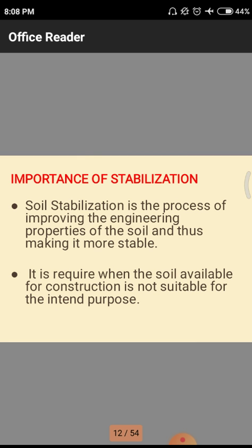Here difficulties means whenever the structure has irregularity of loading and there is no proper stabilization, the structure will show different quantities of cracks, that means lengthy cracks or smaller cracks. Normally we observe cracks in different structures because of differential settlements in the ground itself. Why? Because if there is no stabilization, due to gravity the structure will sink down, so we need to go for stabilization before constructing a structure, and then the foundation will be very strong compared to other structures.